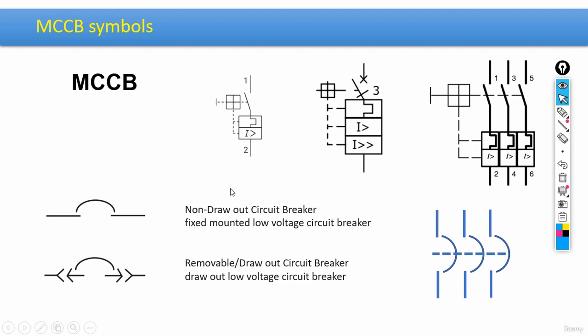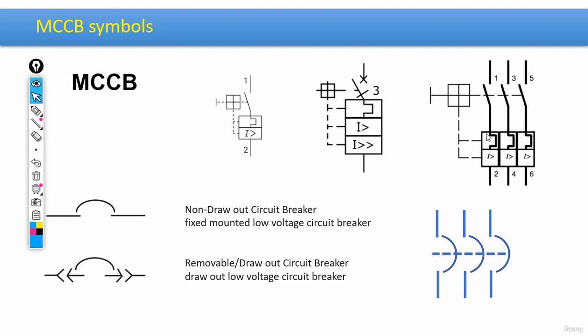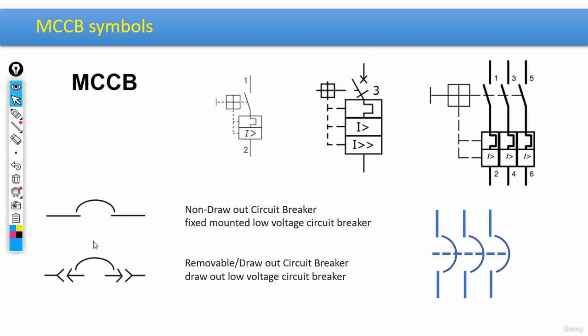For example, we got an MCCB breaker symbol, single line. Okay, this one is also a single line MCCB breaker symbol. This one is used for circuits with high electrical current. Then here we got a multi-line MCCB symbol containing symbols for both, overload and short circuits. Okay? And, by the way, the symbol that you can see here would be the American version, based on the NEMA standards.